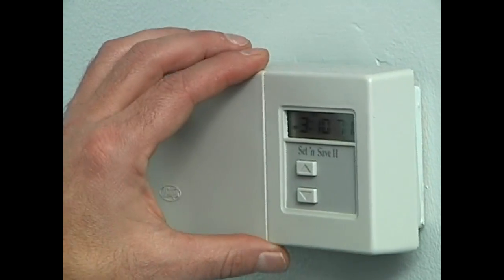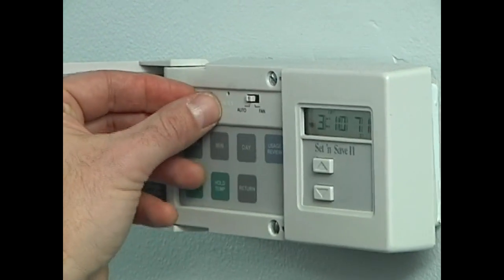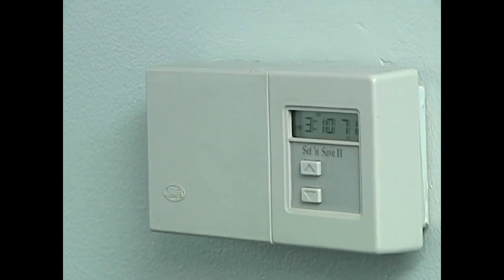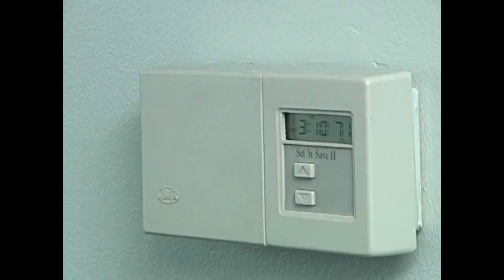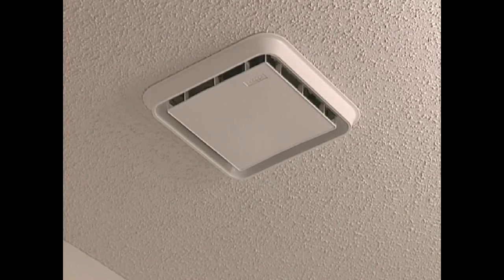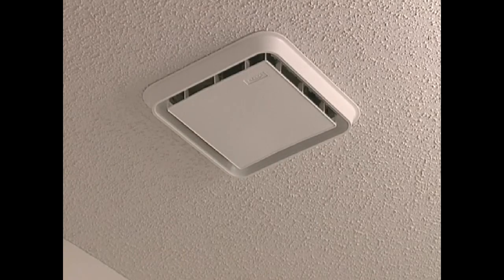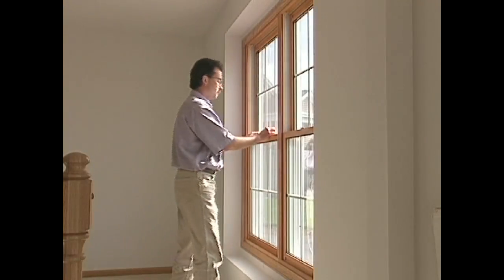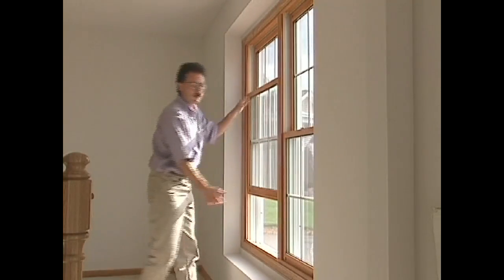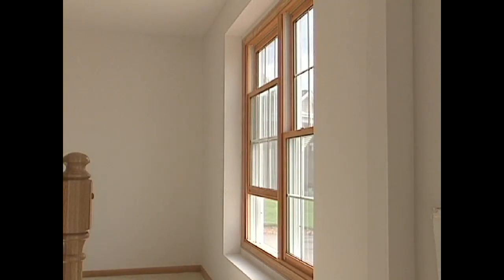We now need to prepare the duct system and the house for the test. First, adjust the HVAC system controls so that the air handler fan does not turn on. Go around and turn off any exhaust fans, vented dryers, ventilation system, and room air conditioners. You will also need to open a door or window between the house and outside to prevent changes in house pressure when the duct blaster fan is running.